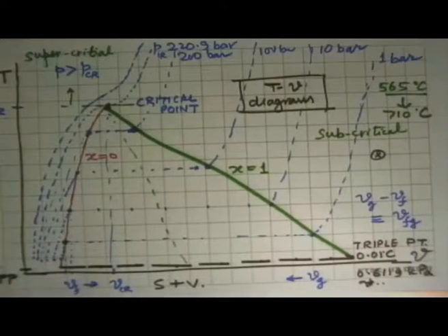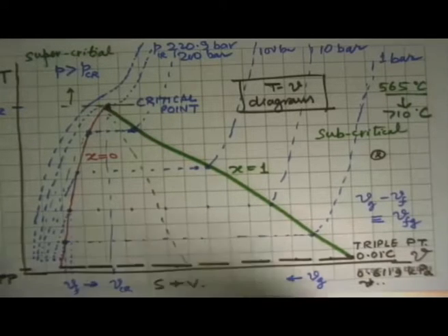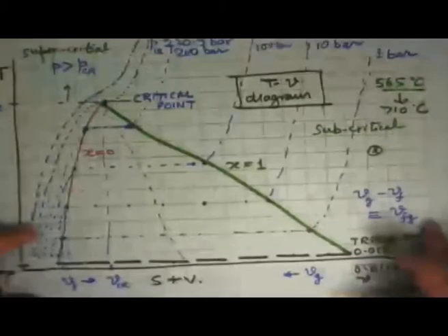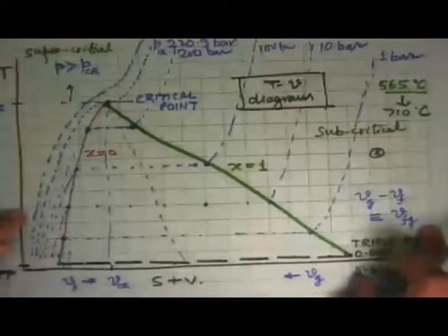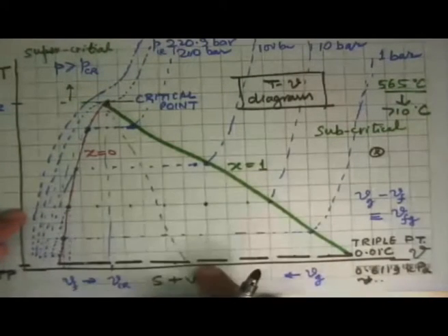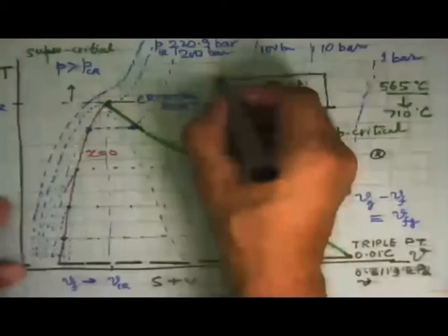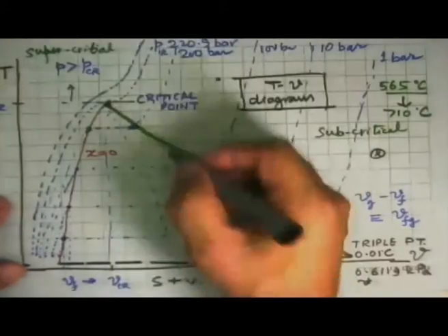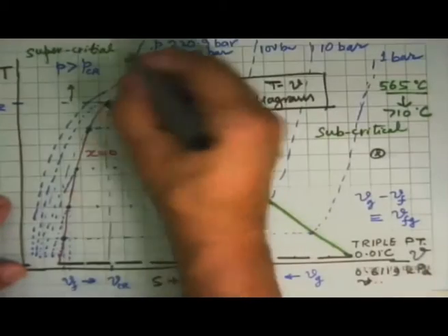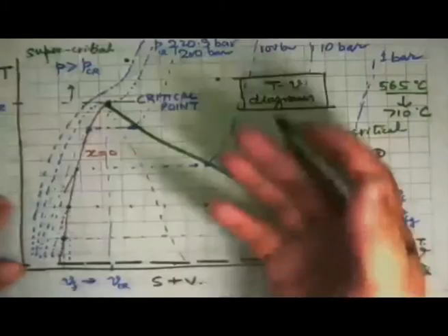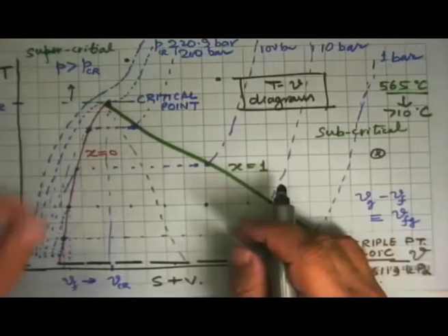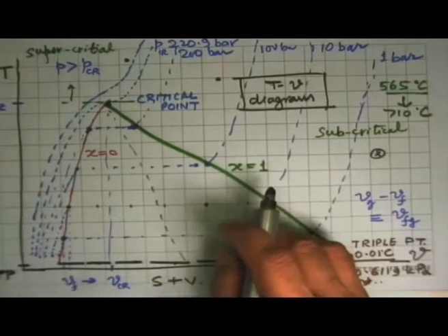And it gives us the ability to tell what will be the state of the substance once two independent properties are known. So if we can locate that the state is, say, here, we know it is a wet saturated state, we can figure out where is the temperature, what is the specific volume, and then calculate all the other properties also. If the state happens to be here, we know this is superheated state. If the state happens to be here, you know this is a supercritical fluid or a dense fluid, you know what the specific volume, entropy, everything else is there.